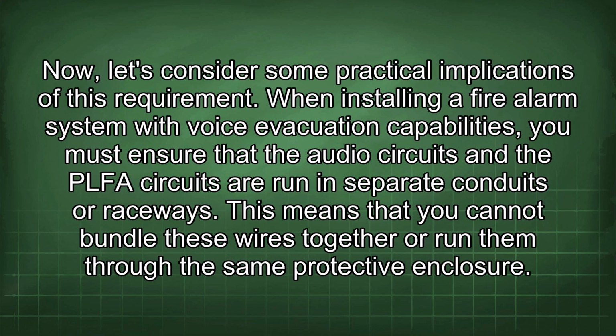Now let's consider some practical implications of this requirement. When installing a fire alarm system with voice evacuation capabilities, you must ensure that the audio circuits and the PLFA circuit are run in separate conduits or raceways. This means that you cannot bundle these wires together or run them through the same protective enclosure.